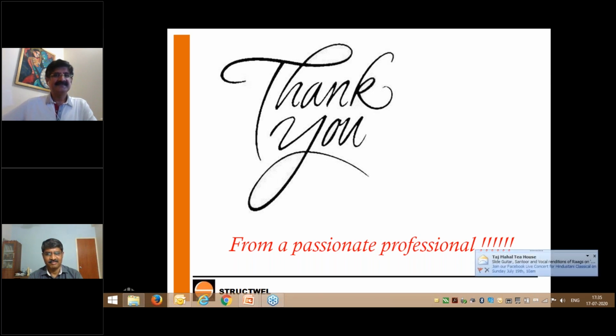I think that is a very valid point he has told all the engineers, because otherwise many people, we have seen, paint the stone facade on the external face. That is very bad. Or they rake out the joints and do the pointing, which is seen from the surface, which is very bad, which is not to be done.